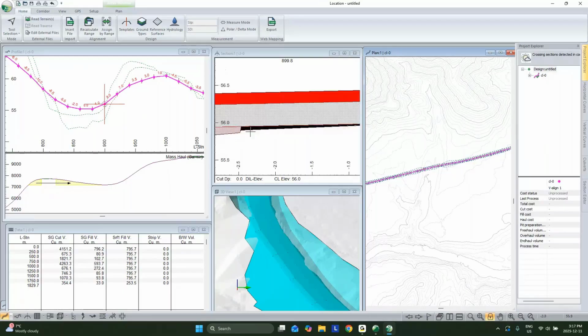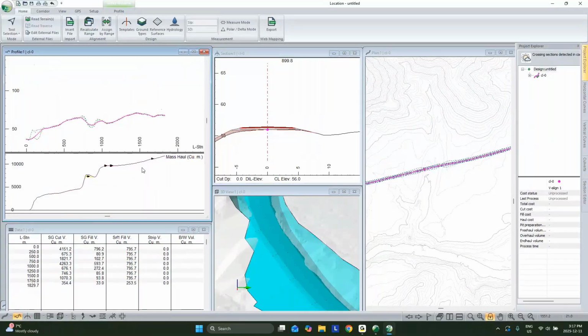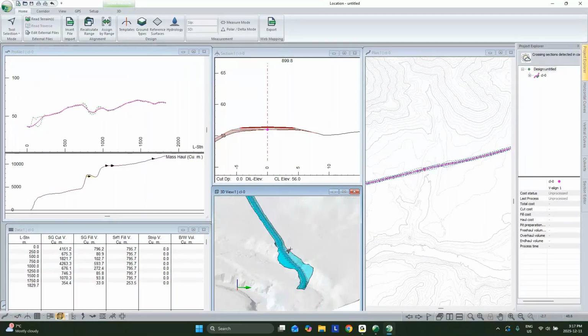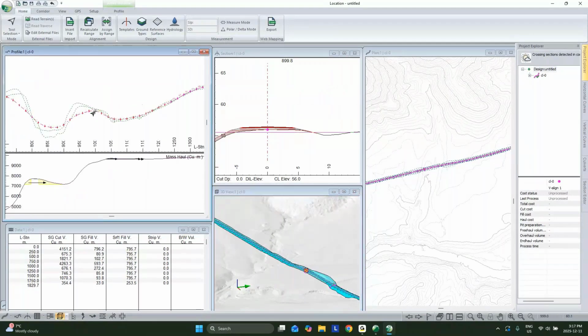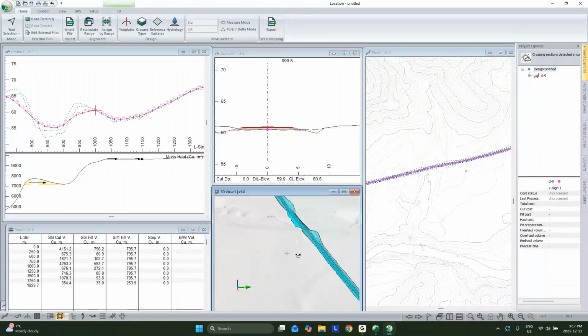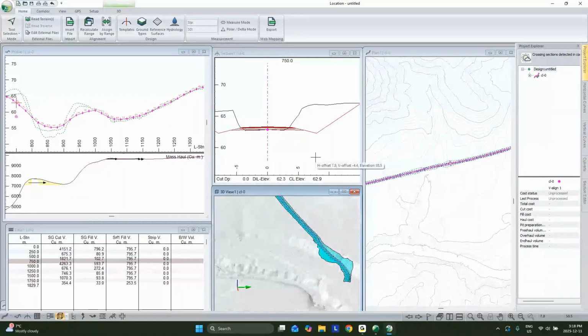And if we zoom in, we can see that that little material here, that surface 4, is being tracked as we'd like. And then we've got the subgrade being accounted for elsewhere. Now with this, if we zoom out, we can see that it's a decent amount of work. Our center line is still exactly where the surveyed center line is. But even with that, we've got a decent amount of cut in spots in order to get that out to meet our preferred cross section.